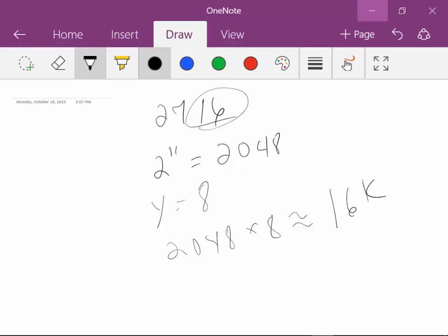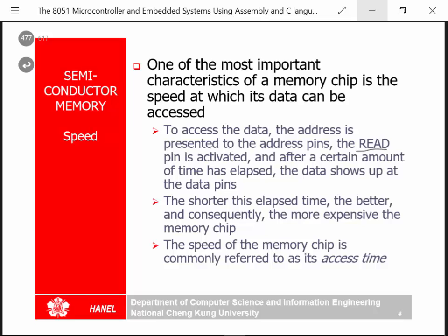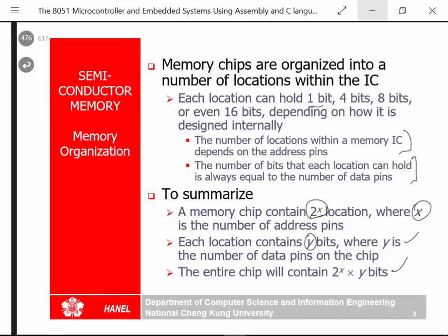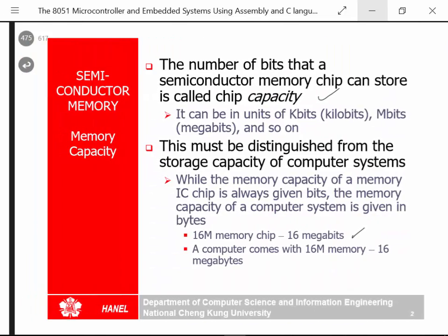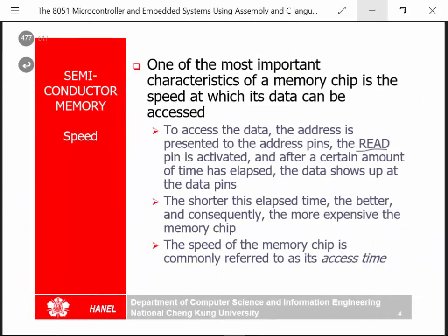The cost difference between a PROM and a mask ROM is probably, I'm just throwing these numbers out, a PROM might cost, say, 5 ringgit, and a mask ROM might cost 3 ringgit. So there's a 2 ringgit difference between the two parts. But it may cost you 10,000 ringgit to generate the mask. So you have to make enough of it. You have to have a large enough volume to justify the process of making the first one. Things we have to look at.